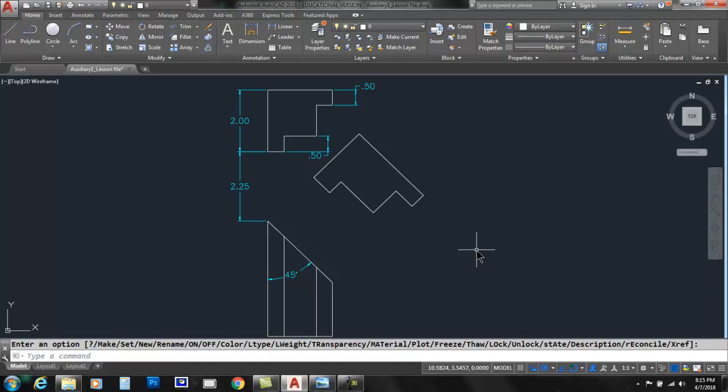Now we're going to continue with this and actually finish the entire view to create an auxiliary view, not just a plane. And what I mean by that is this upper area is correct, but if I took those 90-degree lines and I projected them all from the bottom surface, we know that something else is going to continue happening all the way out to here. These lines will continue downward and we would see something more there. And no, it's not going to be a straight line because we're going to have a similar profile cutting up and completing the view as such.